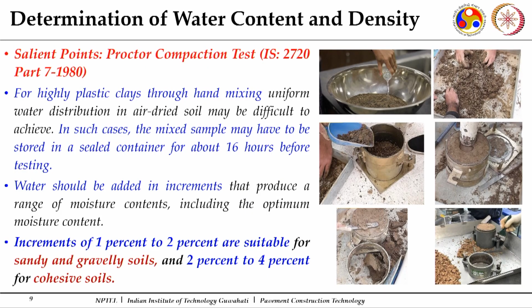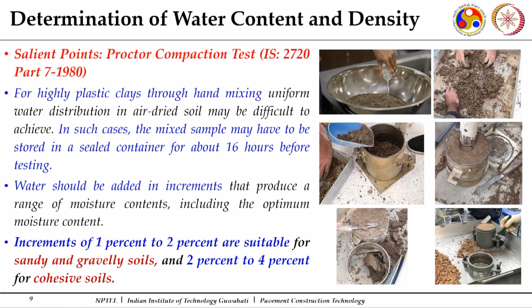Now, another important aspect is that when you are using a clay soil, normally you are doing hand mixing. So, there it takes time. For clay soil, a uniform dispersion of the water normally takes more time. If you do it very quickly, the water may not distribute uniformly among the soil mass which you have taken for your test, and that soil mass quantity will depend upon the size of the mold.